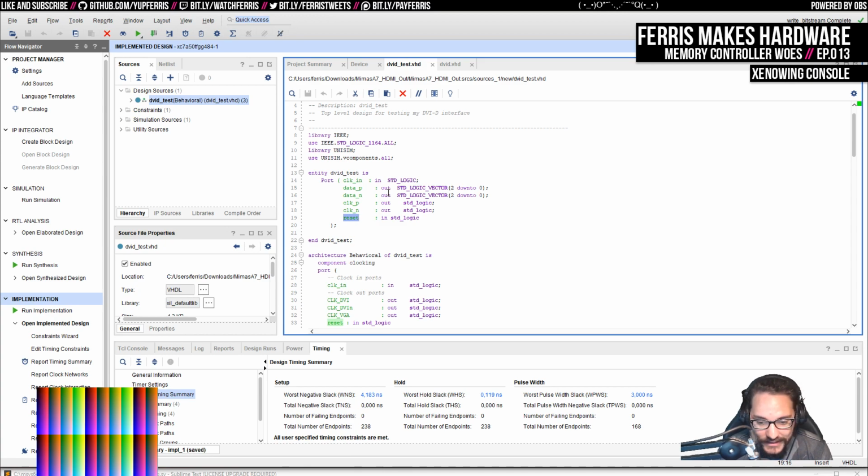yeah, that's probably a really good idea, Daniel Colin, or at least like the MicroBlaze, Vivado, whatever Xilinx has. It seems that MicroBlaze is their general soft CPU core, which, depending on if it gives you a nice compiler for it, might be smart, because then it would be really easy to generate that IP and probably generate the IP that works with that. For example, the Ethernet controller, or whatever else you might need. But I don't know what that's going to look like to make a slave Ethernet device. So there might be something useful there.